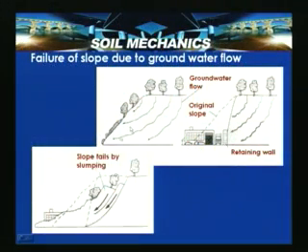So, when groundwater seeps through a slope, this is how it naturally flows. This causes a slope failure, like the soil slope failing by slumping and endangering the stability of structures within the vicinity. This is the original cross-sectional slope, and as it is unstable, it tends to adjust to a stable configuration. In order to arrive at that, the soil mass undergoes movement and fails. This is the failed portion, shown here schematically.